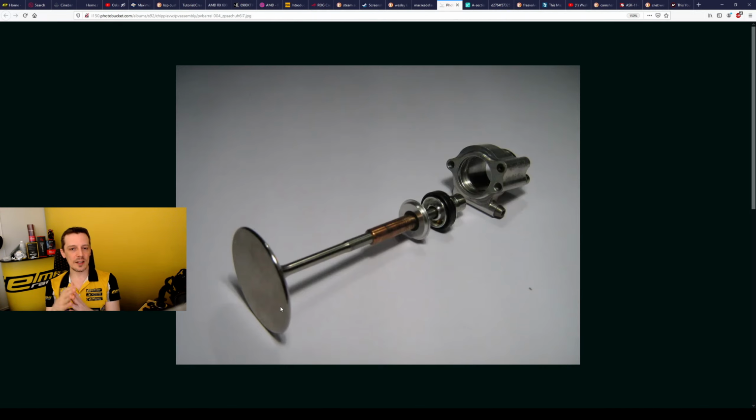The intake valve has a much better time because the combustion temperature is the same, heating the inner surface of that, but then you have the intake charge coming in, and that is much cooler than the combustion gases. So we'll have a cooling of the intake valve, and that typically means you don't have any problems. We will be able to transfer enough heat from the valve dish on the valve seat into the cylinder head to not have issues.